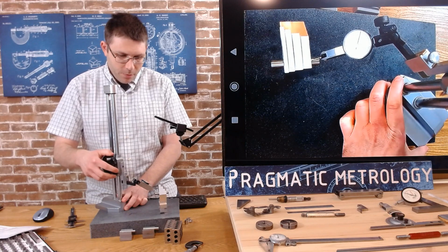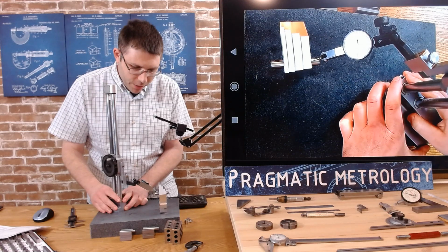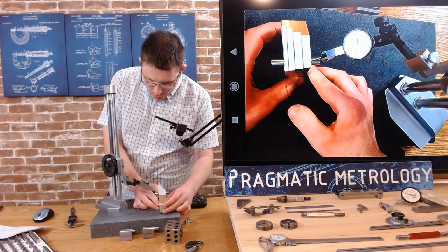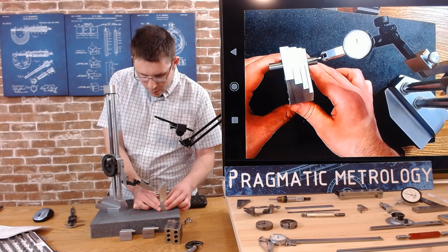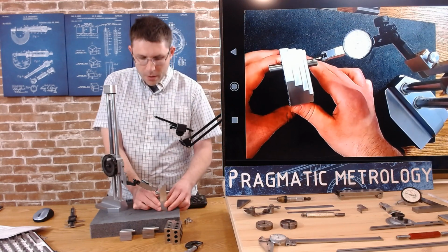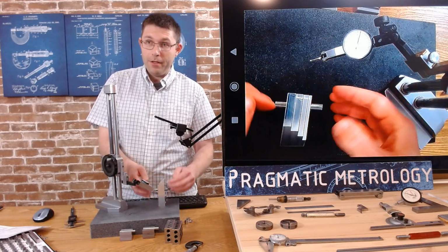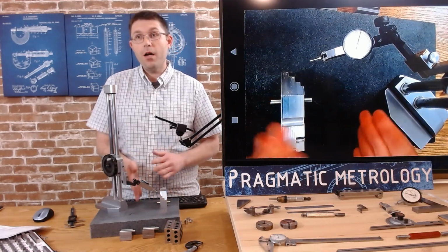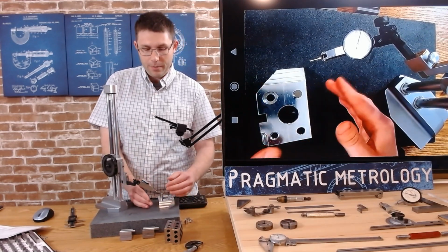So this may be a better way to do it, although we're not referencing datum A anymore, but I am checking if the hole is straight. So I have 0, flip it around, and I have almost 1,000th of error. But once again, this is telling me how parallel it is to datum C. This one is telling me how parallel it is to datum B. Logic would tell us that has something to do with datum A, but that's not always the case, right?